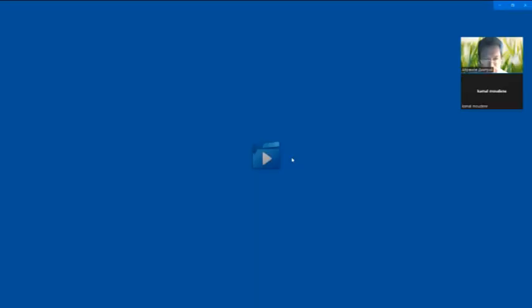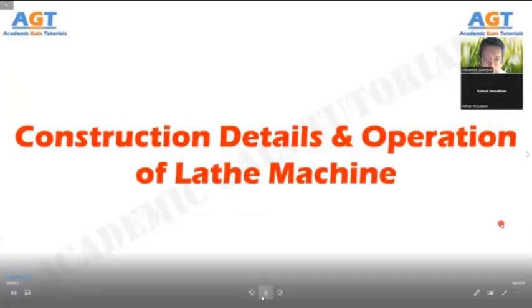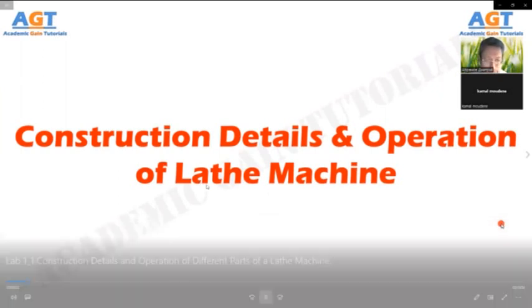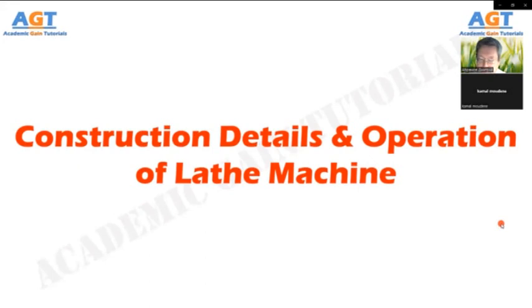First video for today. Welcome to Academic Game Tutorial. Construction, details and operation of lathe machine. So, the function of lathe is to remove the metal from a workpiece in the form of chips by mounting the workpiece rigidly on a machine spindle and revolving at the required speed, and the cutting tool is fed against the work either longitudinally or crosswise to make the work to the required shape and size.